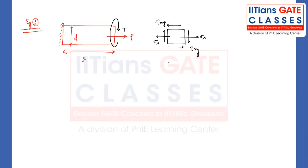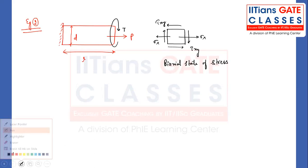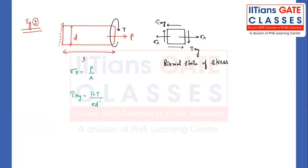So this is the biaxial state of stress condition, my dear friend. Now, understand. Sigma x, everybody knows, is P divided by area. Tau xy, from the twisting formula, is 16T divided by pi d cubed. Now we know sigma x and tau xy. I'll be covering the twisting chapter, that is the torsion chapter, soon, and there I'll tell you how this formula is derived. But as of now, just consider that the twisting formula is 16T divided by pi d cubed.